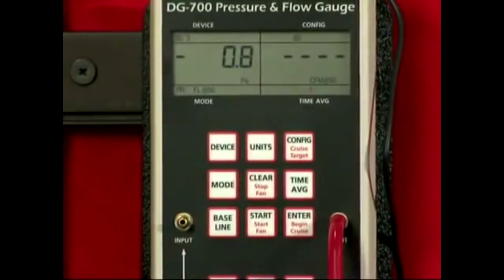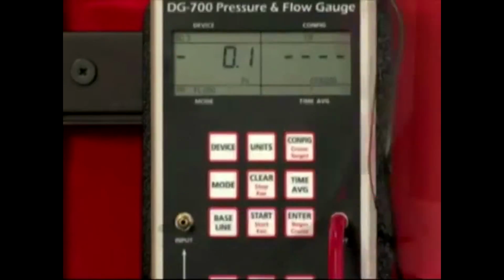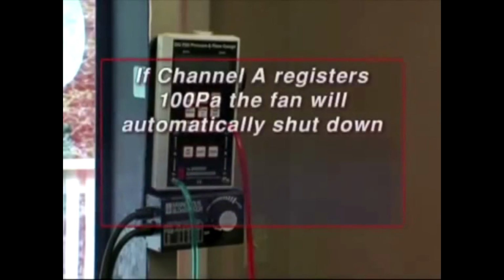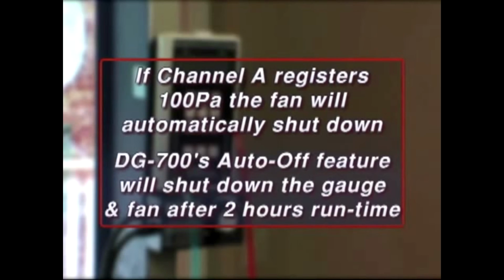Note, if you need to change the configuration setting on the gauge because you've changed flow rings, you'll need to exit cruise before using the Config button to change the selected flow ring. The fan will also be stopped while cruising under the following circumstances. If channel A registers a pressure of 100 pascals or more, the fan will automatically be shut down and the gauge will revert back to the cruise setup state. The DG700's auto off feature will shut down the gauge and turn off the fan after 2 hours of runtime if no buttons are pressed during that time.